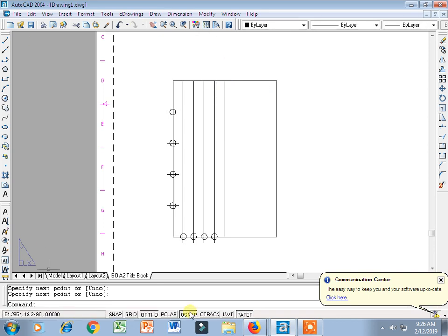Okay. Now if you want, you can give the text also. Here 1 2 3 4 5, like this, we have given the location of the points. Now you give the height like 5, enter, angle 0, and then we will enter the text 1. Then we'll come here and write 2, this is segment 3, this is 4.